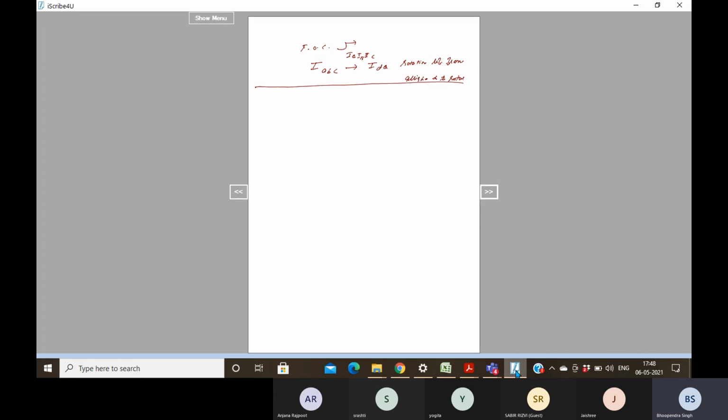Now in direct torque control, DTC, we are going to have a transformation from the natural reference frame to I alpha beta, or VABC to V alpha beta, or lambda ABC to lambda alpha beta. Now, just from common sense, which is less complex, this one or this one? Which algorithm do you feel should be less complex? FOC or DTC, or simply working in rotating reference frame or working in a stationary reference frame?